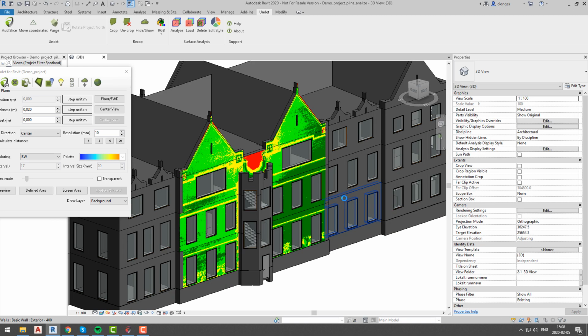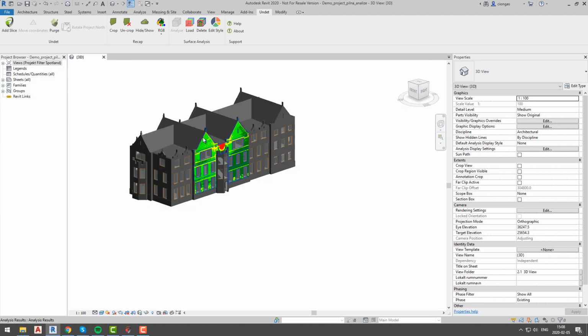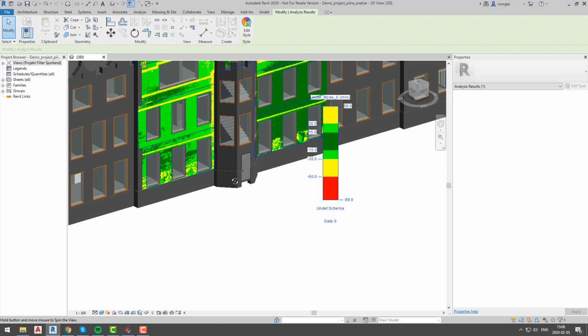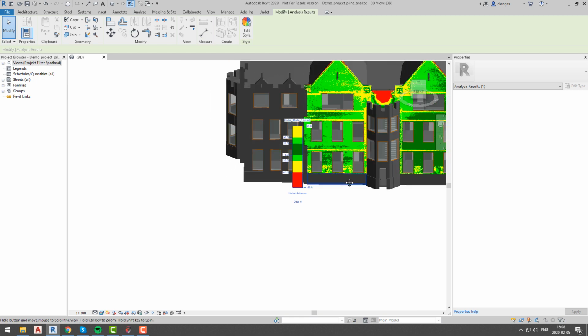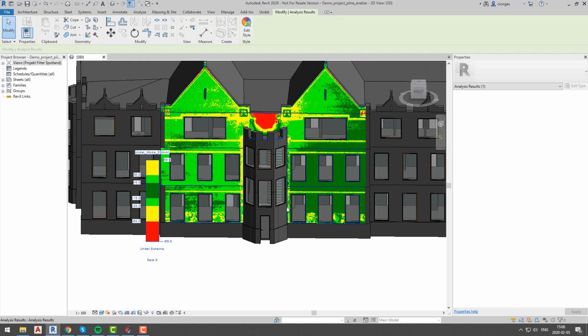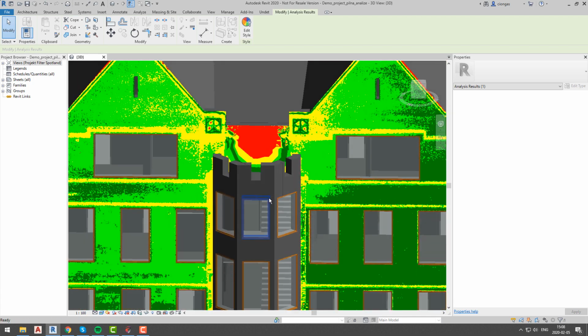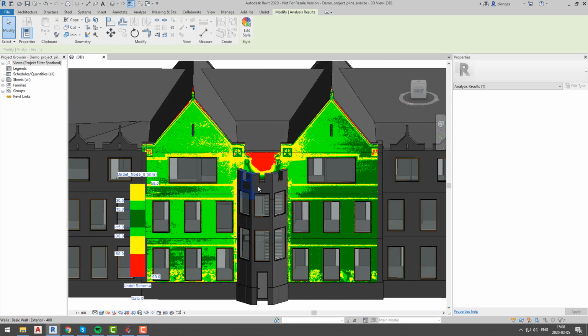As you can see our model is mostly green so walls were modeled correct inside tolerance boundaries. Red spot on top is because building was scanned from ground level and these points were not visible, and those red spots in corners are facade elements which we did not model, that is why we see them as mistakes in our deformation analysis.